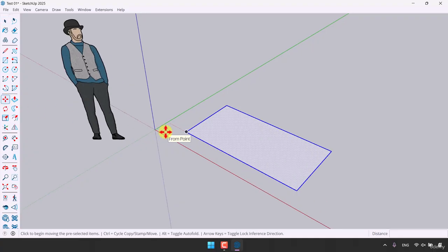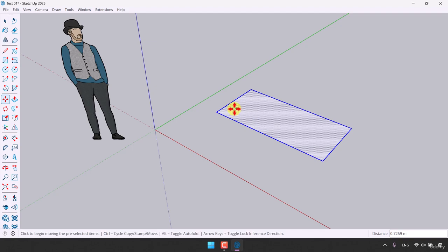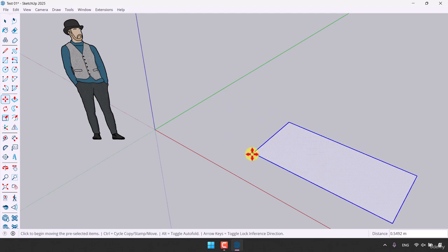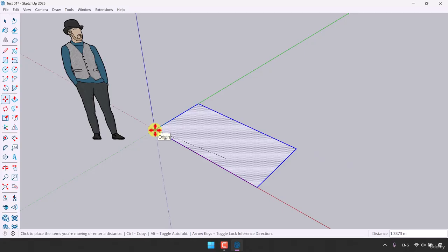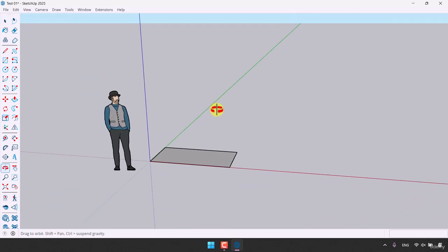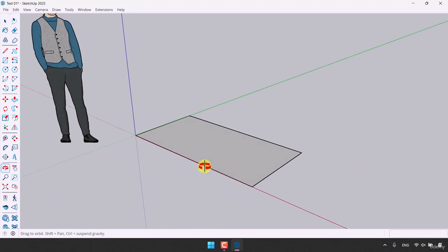Click on the move, and now you can move it from different parts, different places, different faces, different vertices. It depends on you, but if you want to work accurately, you need to move your cursor near to the end point of your 3D model. So I'm going to left click on it and move it to the origin point. The snap is activated, and you can left click another time and press space. If you want to totally exit from it, you can press Escape or click on the other places of the software. So very simple. We draw a line like that.